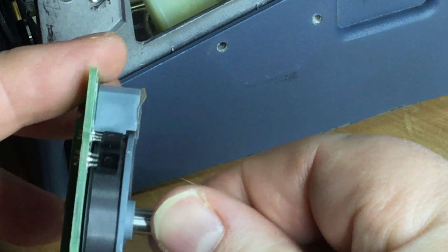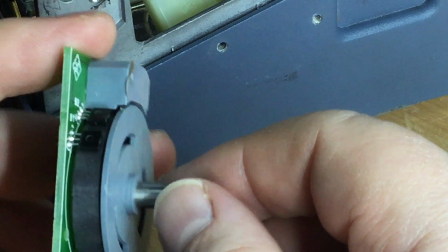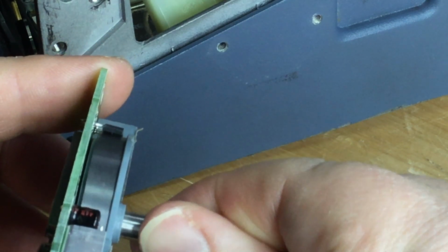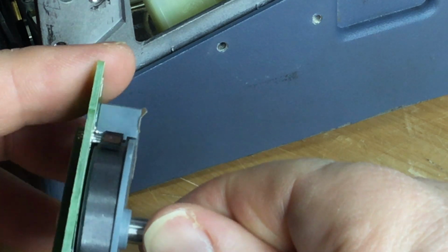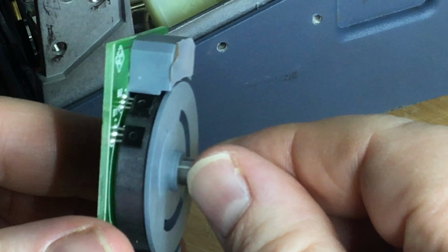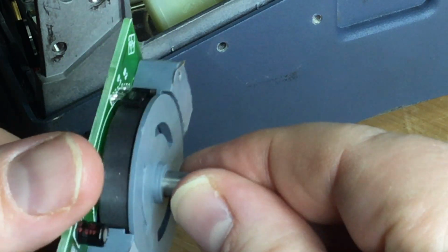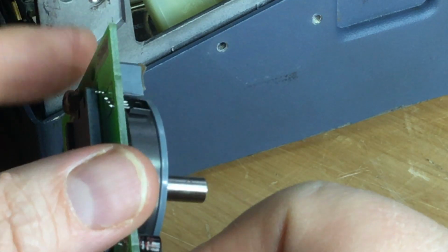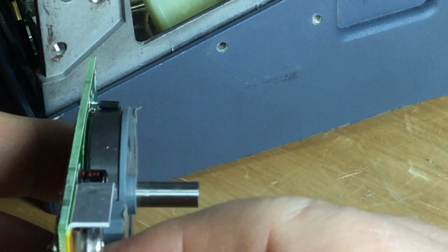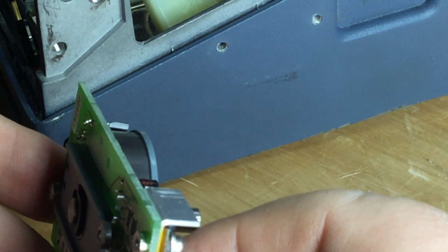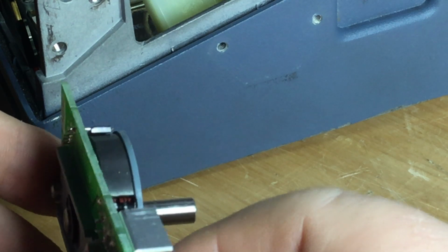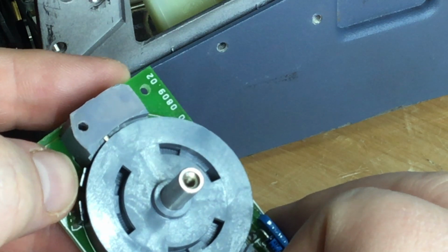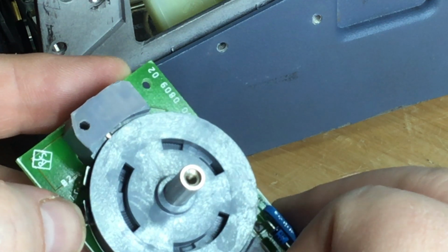So I'm wondering if it's contaminating these Hall effect devices, and we're getting some contamination on them, maybe. Possible, may not be. So might be worth a look at that. And it could also be that those Hall effect sensors need to be pushed up against the magnet a bit more, or perhaps even brought out, because one of them looks like it's pushed up against the magnet more than the other one is.